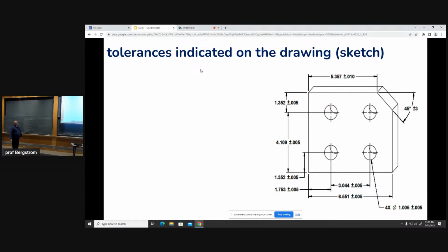Okay, what if we can't do that? What if we don't have that skinny vise? Yeah, so I could make one side flat and smooth. I could do it by sticking the part up in the vise and doing a facing operation. I could do it by having the part hang out the edge of the vise and doing a contouring operation. I could do it by, I don't know, very patiently pushing it up to the sander and making it square. Don't do that last one.